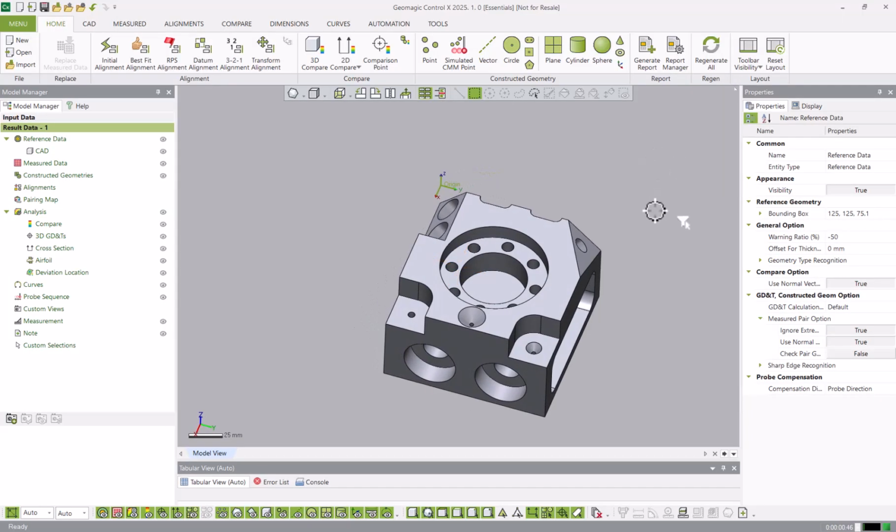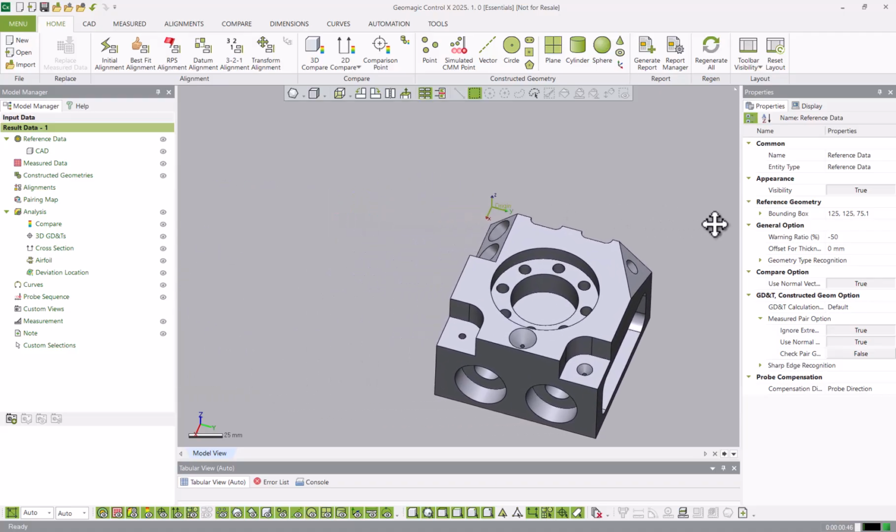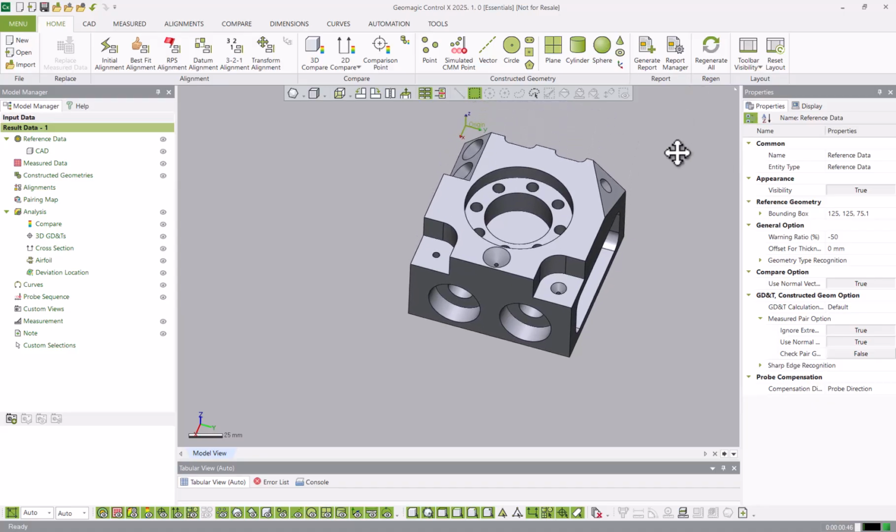And in order to do a pan action, it's also quite simple. You can click and hold your right mouse button. Now click your left mouse button and hold it. When both of them are held, you will see the pan icon come up in white, and you move your mouse towards the left or right in whichever direction you want to move.